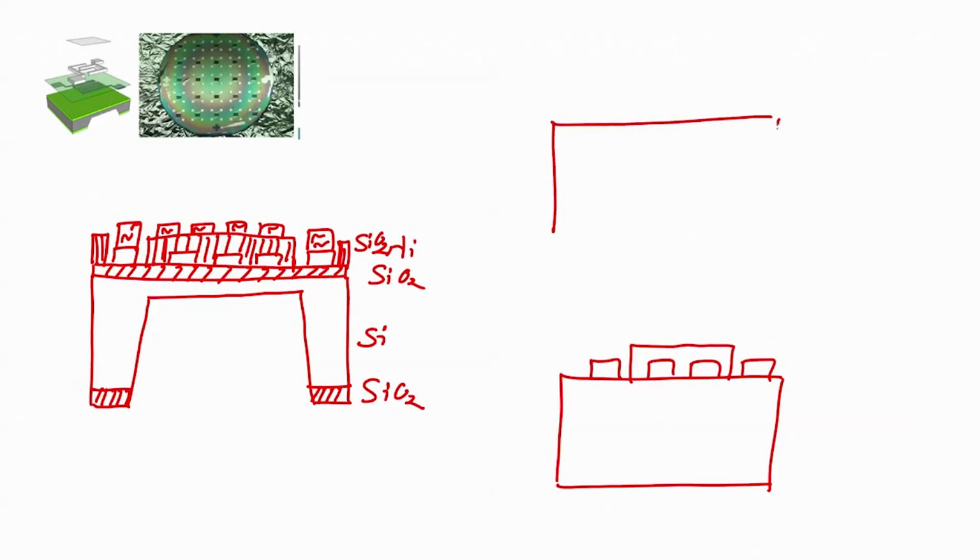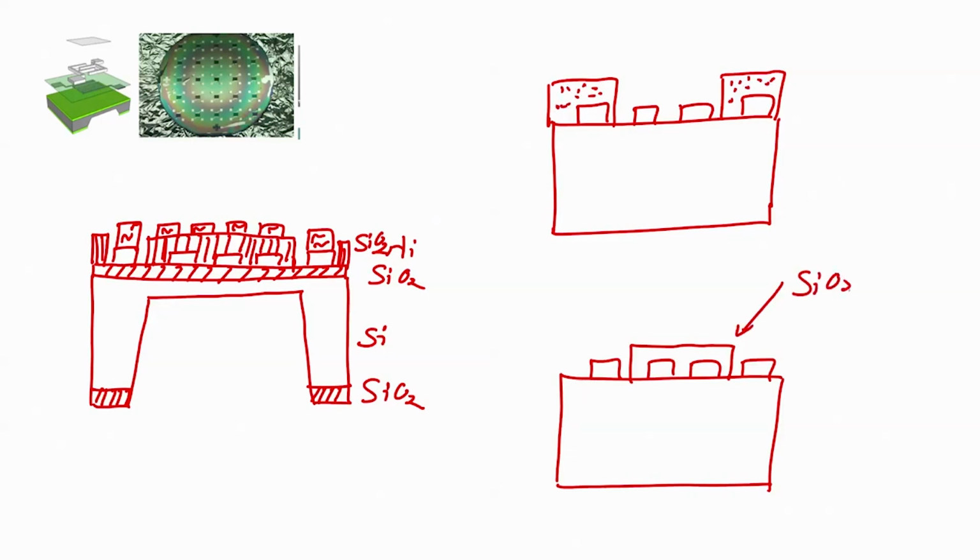I take the wafer with my aluminum interdigitated electrodes, right, and I coat the photoresist in such a way that my photoresist will cover only these two electrodes. This is my photoresist. What I want? I want silicon dioxide, I want aluminum. So, let us have aluminum like this, it is easy to keep the pattern same, right.